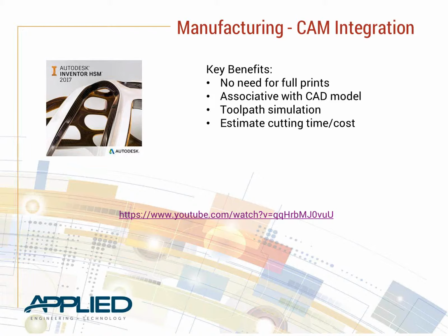Yeah, the part that's interesting is when you start to get into being able to watch the tool path go, know that you're not going to hit any areas where you're holding down the part in different areas like that. You can really estimate how long that part is going to take to get cut. So you can even go back and forth with that a little bit and find out, yes, this is a part that's going to be cut and it's going to take this long, and we know that the burden rate for that particular machine is so many dollars per hour, so we know it's going to cost this much. And that's what we're just trying to roll up to.